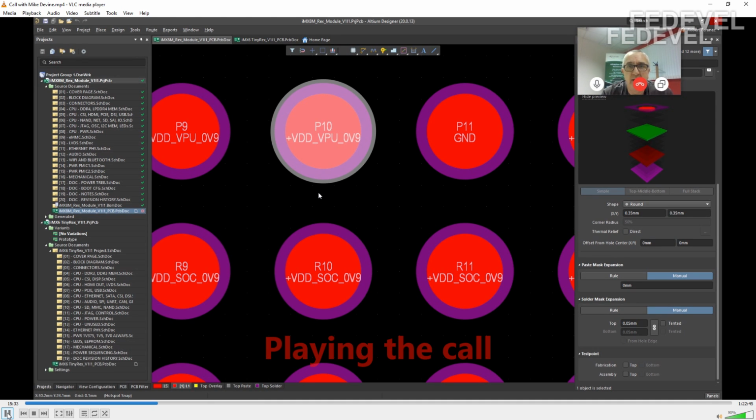Because then that allows the vacuum assisted resin fill system to fully fill the plated hole. We have to drill those holes first, then plate them, and then resin fill, and then plate over the top. And so the ratio would be like 1:10, or sort of, for a 1.6 PCB, the 0.2 is fine. Yes, you're looking at an aspect ratio of 8:1, which is fine.